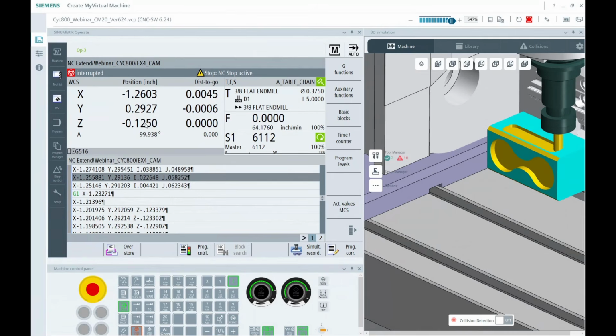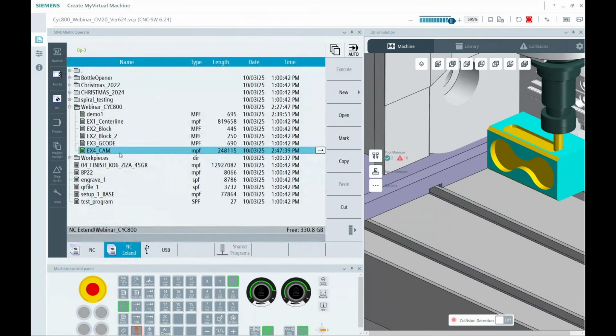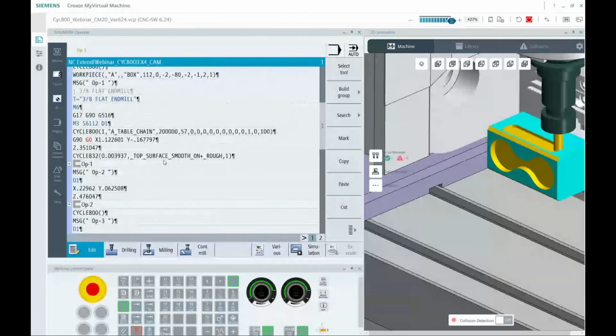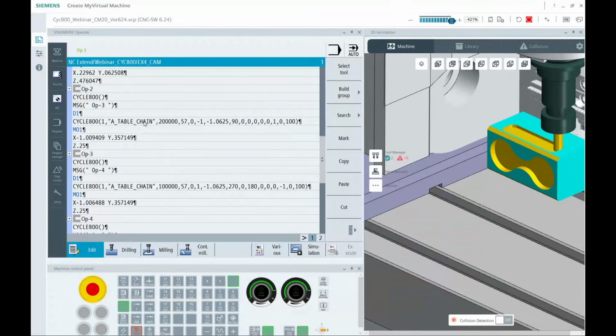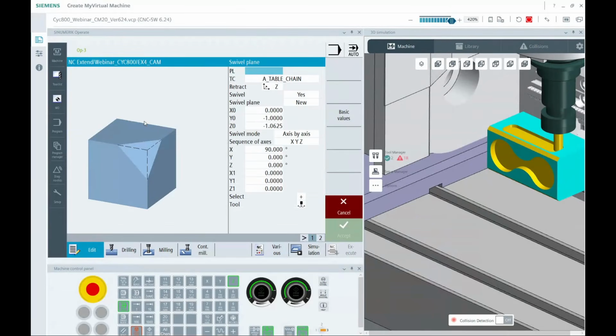It's about to start machining this pocket depth. And when I stop, you see how my Z is telling me, oh, I'm an 1/8 inch deep from this surface. That's only going to display this way because if we look at the cycle, that's going to be the op 3. It shifted the coordinate system back. So now my depths are relative to these planes.